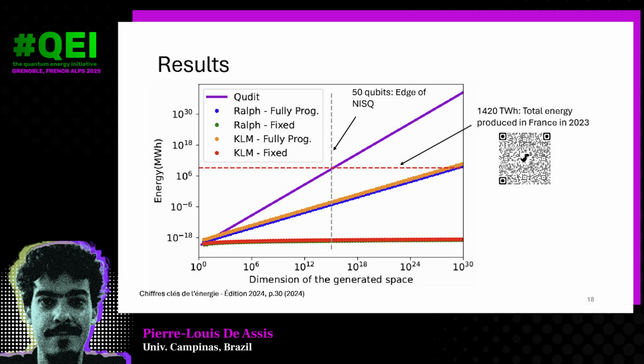I agree. And so the EOM approach, I think eventually it will become standard, but it's a very nascent technology. And still, the thermo-optical modulators can be much shorter. Ours are like 200 microns long, and here you have 5 millimeters long to have about 4 volts of Vπ. If you want to go to 200 microns long, you'll need about 100 volts per capacitor. And then you need to think about the power consumption of the amplifiers you will need to put this voltage into each capacitor. So you shift your problem from one way to the other, and maybe it becomes less efficient.